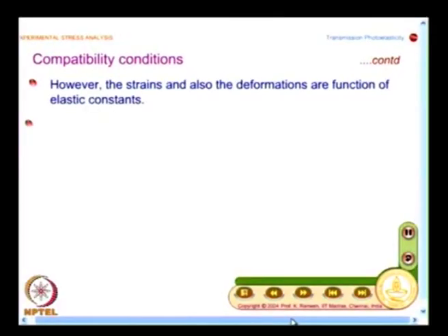But what you find here is, working on a plastic is convenient from the optics point of view, because it behaves like a crystal. I have birefringence, and then I am able to visualize the stresses, all that advantage we have when we work with plastic, and the results also can be correlated to metallic prototypes from the strength of the equations of theory of elasticity. When we go to 3 dimension, what happens? We will see that also. The comfort you have in 2 dimension is not the same. 3 dimension is always difficult. You will have to live with problems.